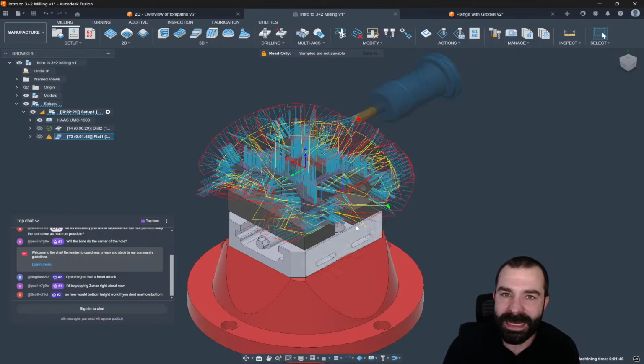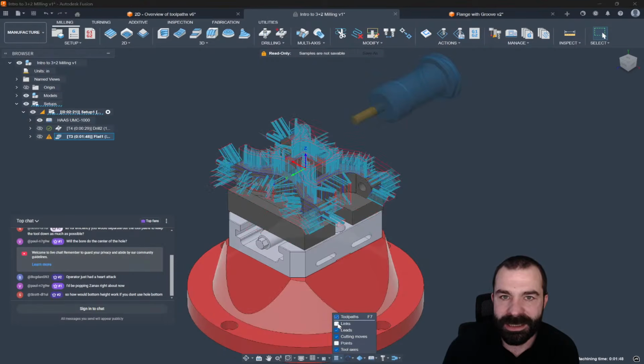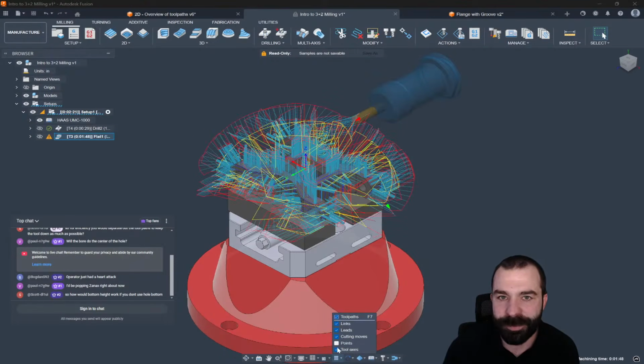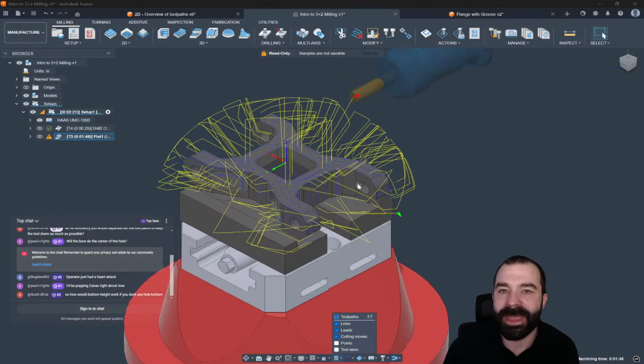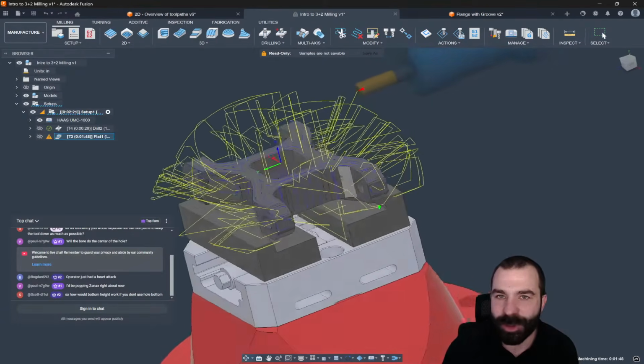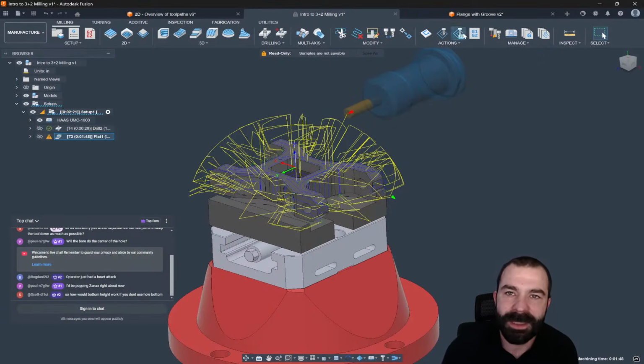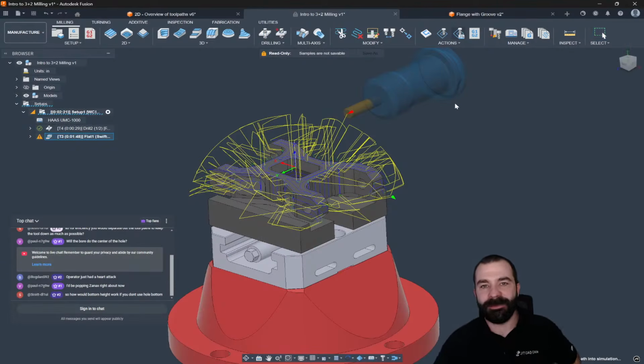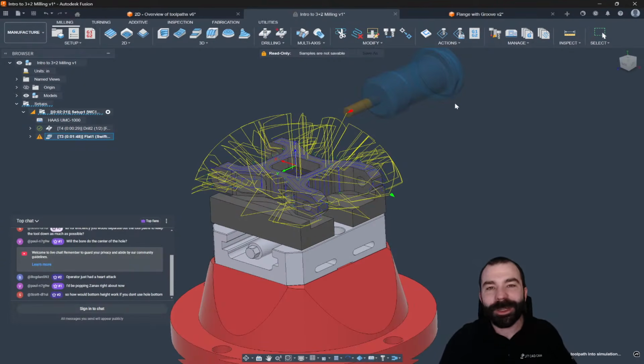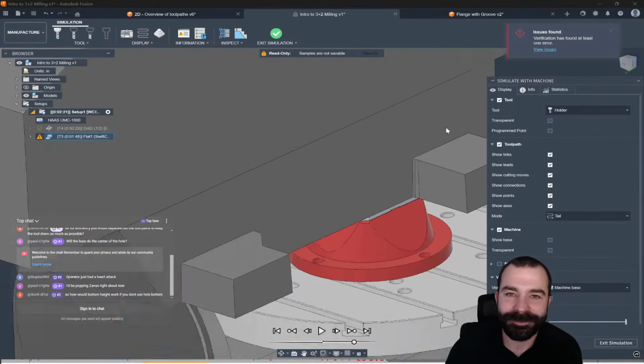So with that, we're going to go ahead and let this calculate out one more time. But again, as you guys can see, a little nicer toolpath. I am going to turn off some of these visibilities. So again, as you guys are going to see, if I remove the tool axis, that yellow line definitely shows us when we're jumping from area to area. And we could simulate this on the machine, noticing that we're a little more forgiving now.